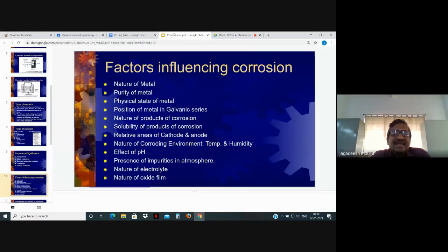In the areas where they are present, they act as crevices and as oxygen concentration cells, making the corrosion progressive. Most of the times this dust tends to absorb corrosive materials and keep them in place for a longer period of time, causing corrosion. That is the reason we do de-dusting of our equipment and cover our equipment after cleaning, in order to avoid this problem.